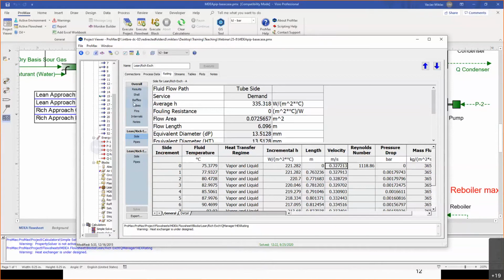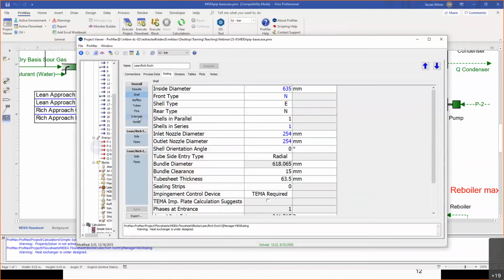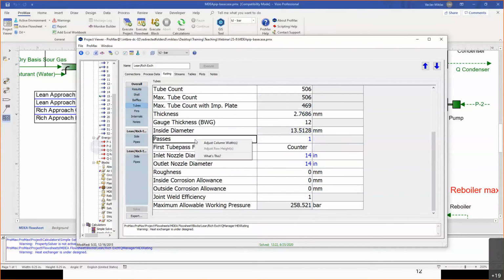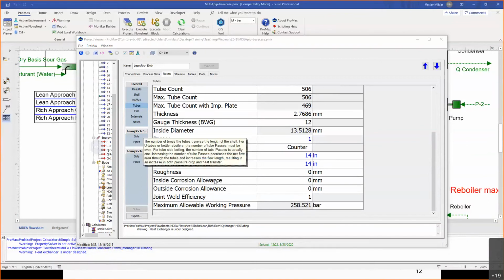So what might be doable, even though it would of course mean some cost, is to use some sort of turbolizer, for instance, on the tube side, maybe plug some tubes. What I'm going to use here is multiple passes, which would probably be a little more complicated in terms of doing the adjustment, but it could still probably be doable.